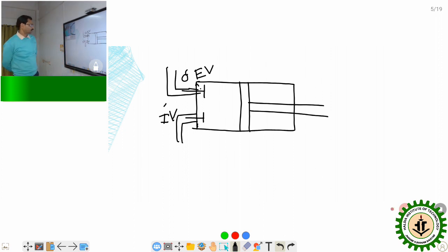And here will be the piston. Through the inlet valve, the air-fuel mixture, meaning petrol plus air mixed within the carburetor external to this cylinder, will go into the chamber through this port, and the inlet valve will be open. So here will be the charge.